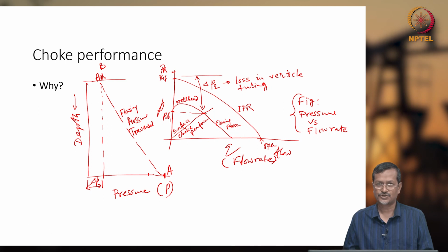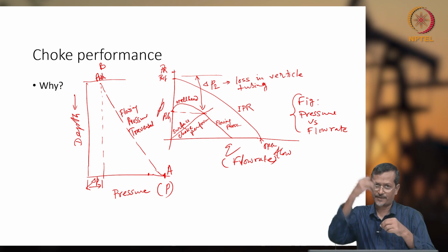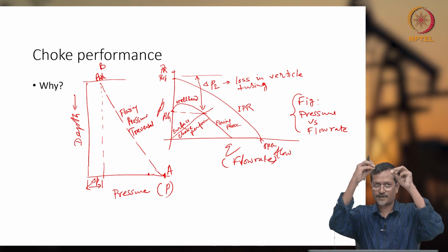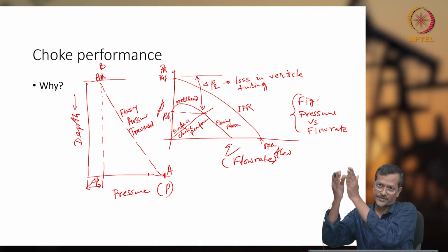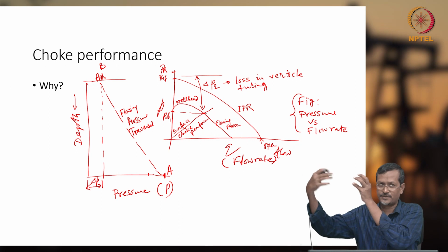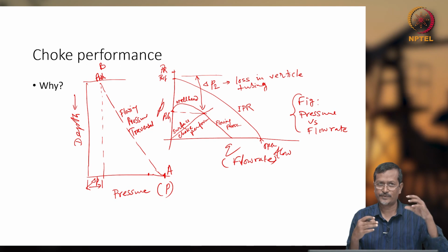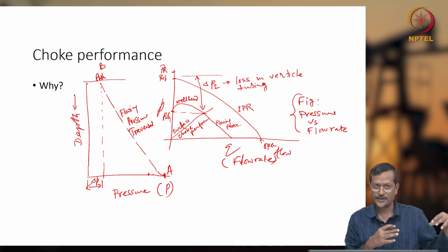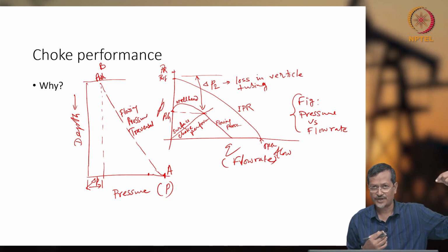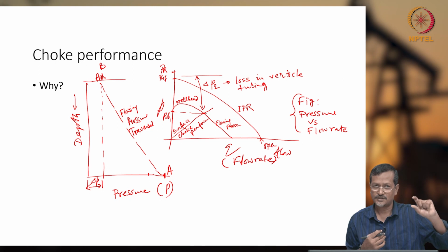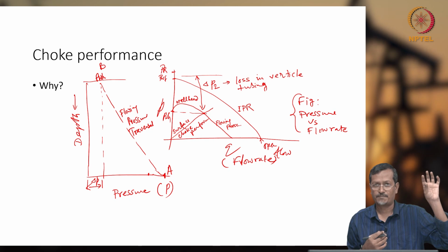And because there are several restrictions in the reservoir, sand face completion, there will be some restriction in the reservoir, piping restriction, wellhead, lots of connection mechanisms, there will be some restriction, choke restriction. Then you are reaching your surface separator system, again there will be several pressure drops, then finally you are reaching your stock tank barrel. And this whole system will be driven by your reservoir pressure only. Actually, if you are giving extra pressure using artificial lift or other mechanism, that means you are giving some extra energy. That extra energy comes from electricity, or you are burning fuel somewhere, and that will cost money.